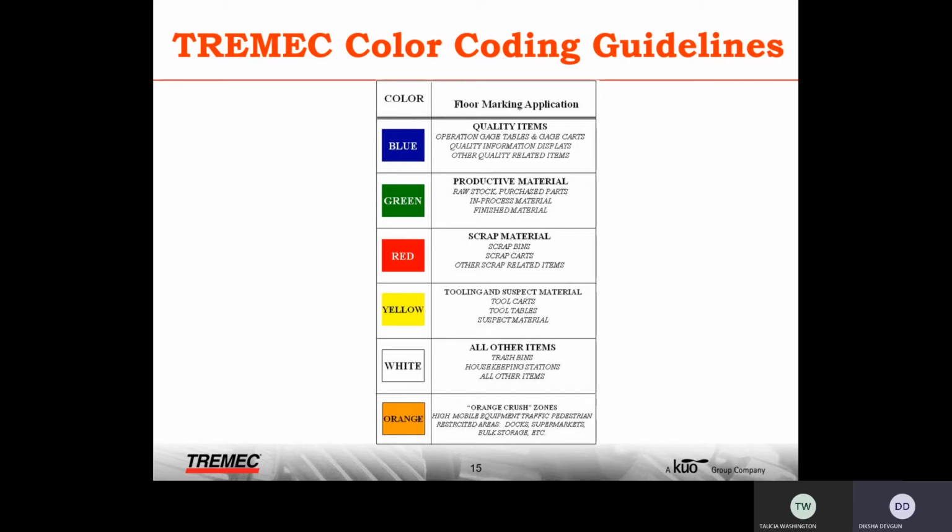For example, once you run the line, there is a pinion station or BIQS station. A lot of the times, if our patterns are not right, we will take the transmission out with the parts in it, and we will just label it as yellow, and we're going to fill out what the reason is for taking it out from the line. It's really important to follow those color coding guidelines and also fill out your tags properly for people to identify what the issue was with it and where it can be reintroduced.